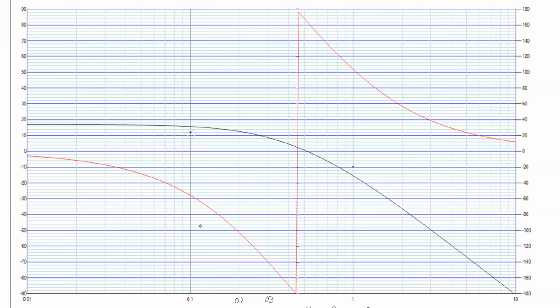This gradient is defined by a point here at 0.1 and 1 decade higher, a second point which is negative 12 dB smaller. So this is wrong. This is plus 12, so we need 1 decade higher and the 0 dB point. So you see, if I draw a line between this point and that point, then we have here 12 dB and here 0 dB, and this is completely from there to there 1 decade.